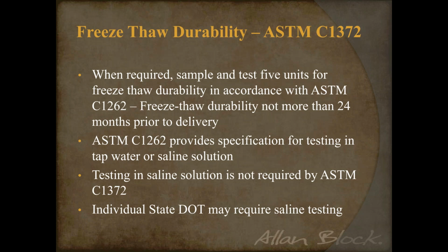But it makes it clear that if the testing is more than 24 months old, the results of that testing cannot be used for the project. So we always work with our producers and make sure they know if they need to keep their blocks up to durability standards, they need to make sure they're testing their mix design and their block well within the 24-month period, so we have standard up-to-date testing.